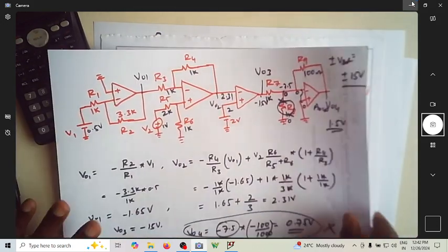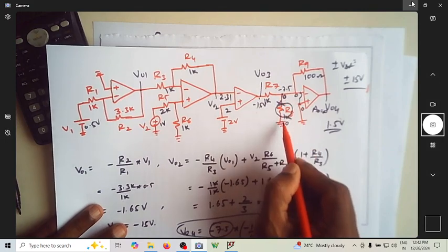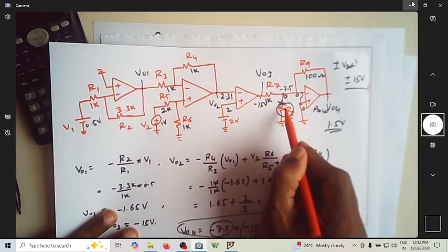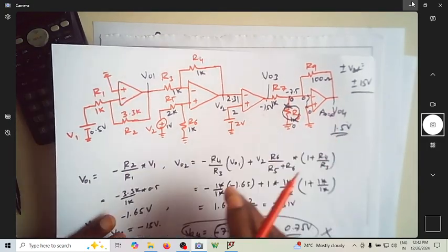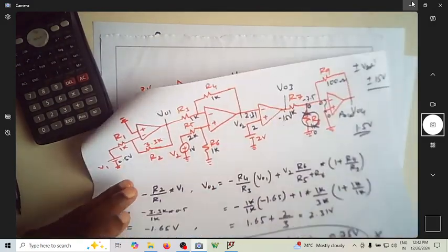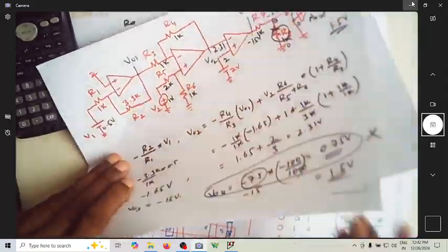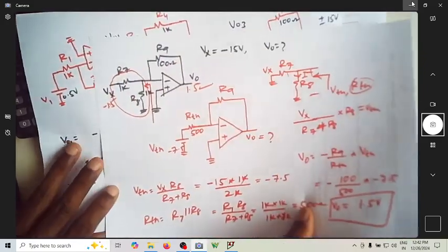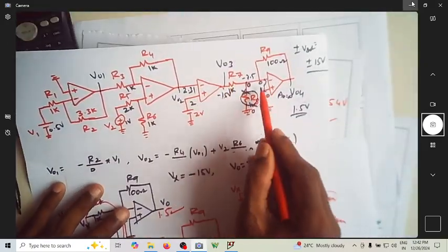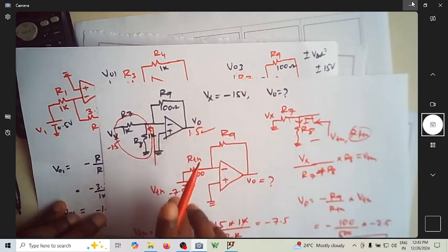In the previous case, we considered it as redundant because the voltage here was the same. Now, don't take it as redundant at all. So you solve this by finding R Thevenin and V Thevenin so that you do not have any ambiguity. So what did I do here? I replaced this part of the circuit, R7 R8, by something like this.